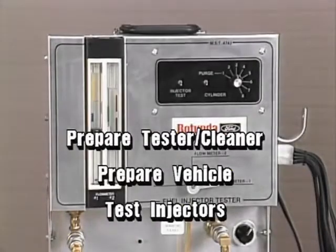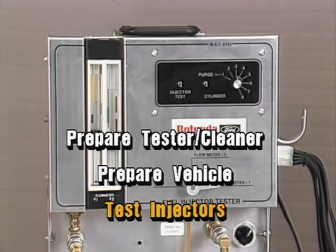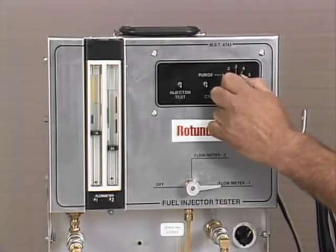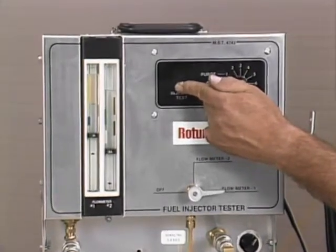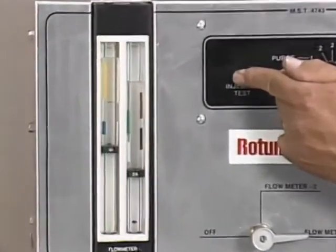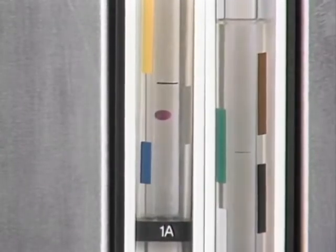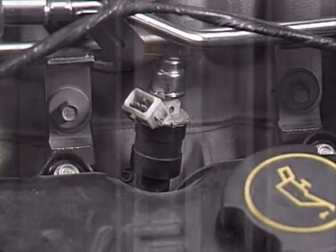With both the tester cleaner and the vehicle prepared, we can now test the fuel injectors. To test each injector, turn the injector selector switch to the number for that injector. Press and hold the injector test switch and observe the flow meter. When the float stops within the correct range for the injector being tested, the injector is OK. This car has gray injectors, so the gray bar indicates the correct range.